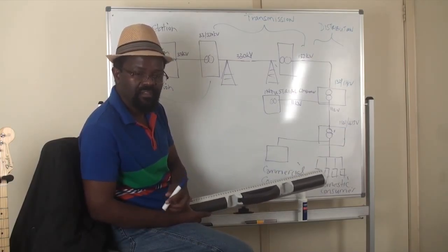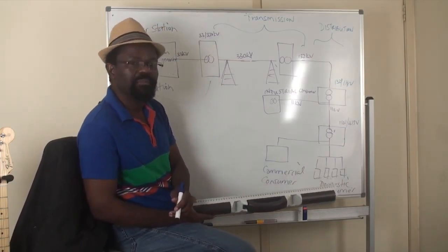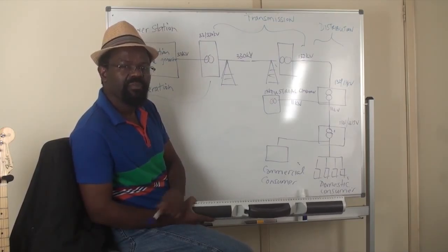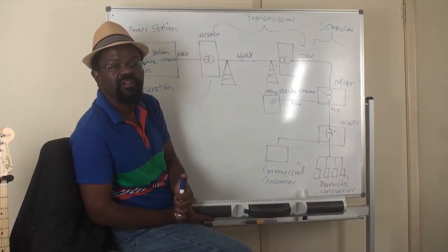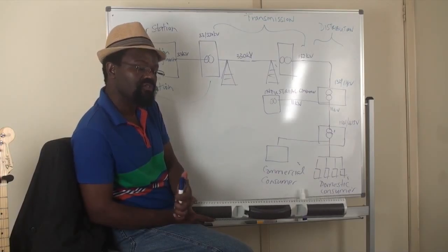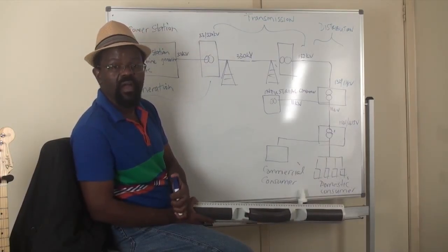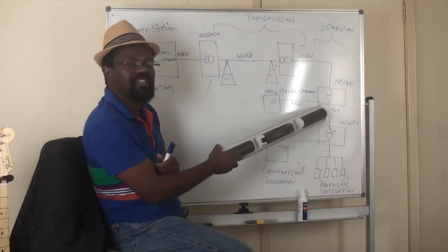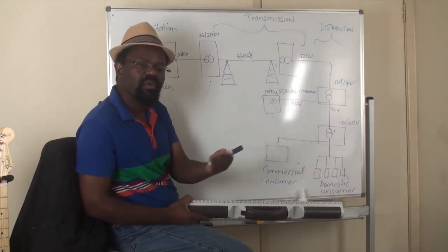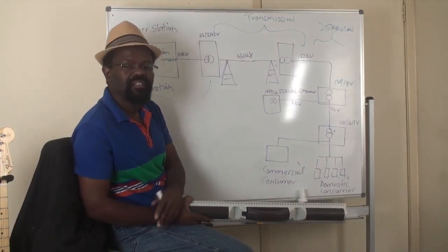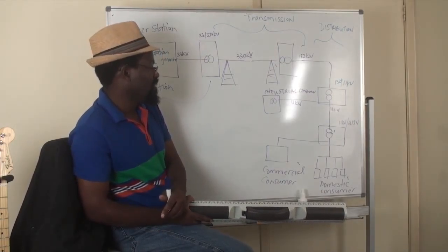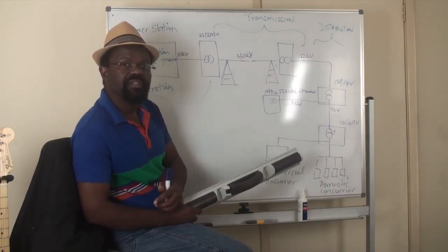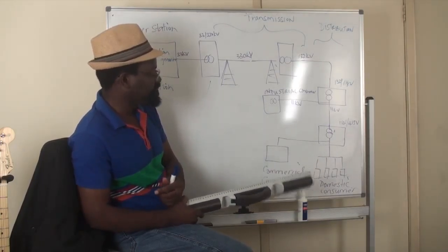Especially the ones in the CBD areas might have their own substations in their own building, because their building might be a big one that consumes a lot of power. So they might need power at a higher voltage. You might give them 11 kV or 6.6 kV or 3.3 kV, depending on their size. So this is the general arrangement of a power system.